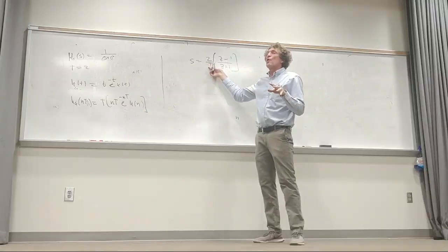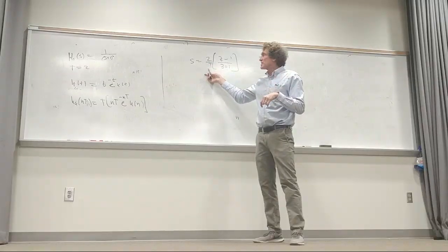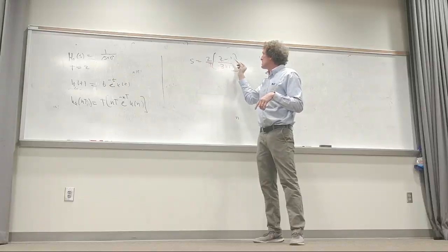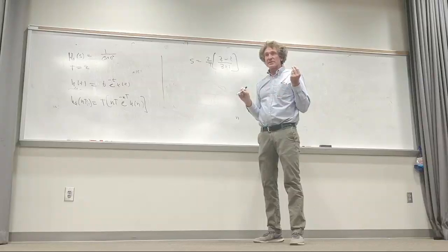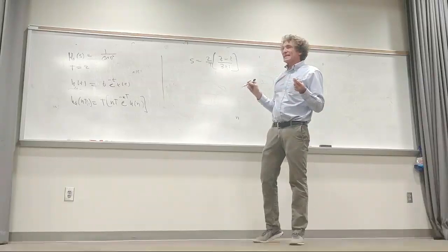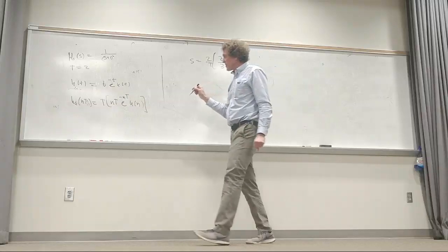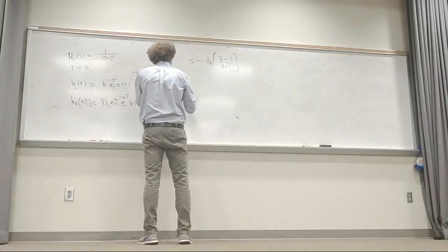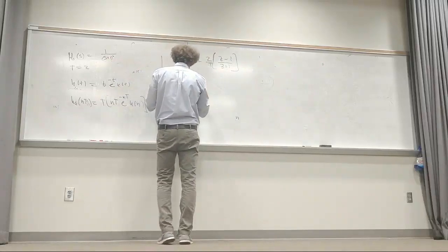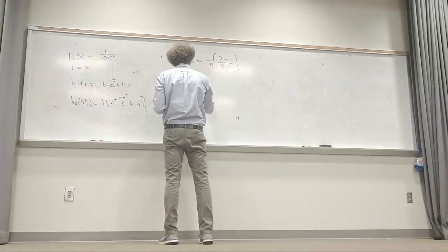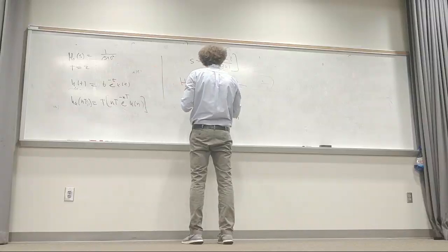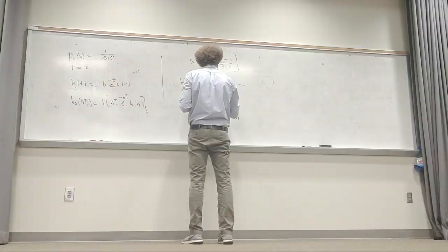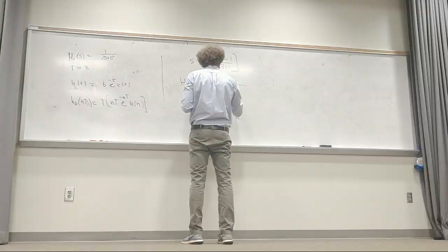It was natural log of Z over T, but we did the approximation where natural log is 2 times (Z minus 1) approximately over (Z plus 1). All right, now pay attention to this. That's S, right? So I come over here, and I say now my H of S is no longer S, but it's going to be Z. And now I take 1 over the quantity 2 over T times the quantity (Z minus 1) over (Z plus 1).